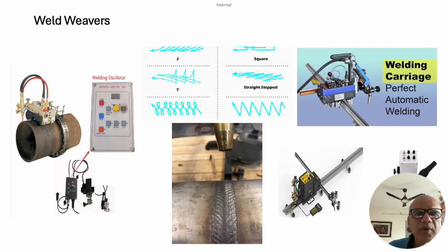So even if you quickly move from one end to the other, and normally we do this 2 to 3 times the diameter of the wire, or 2 to 3 times the coverage a stringer bead will give, or it can be 2 to 3 times your ceramic nozzle, depending upon what kind of material you are using. So if the parameters are good, you don't require dwelling.